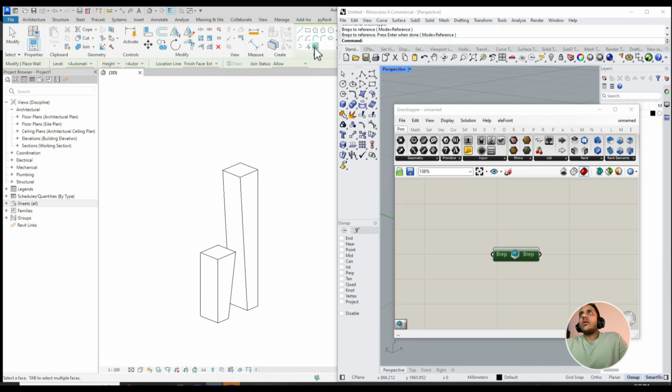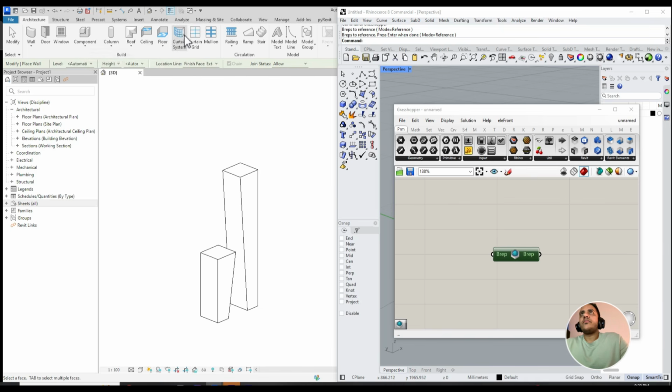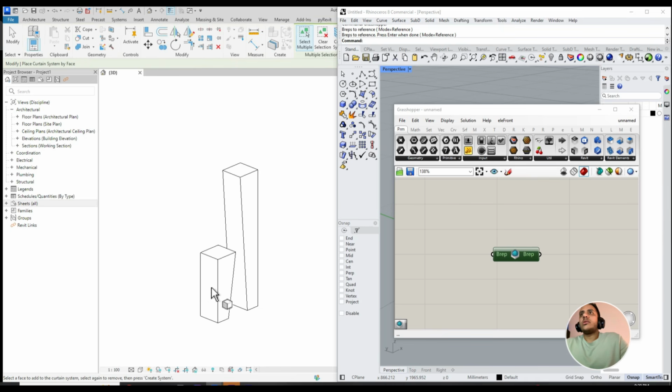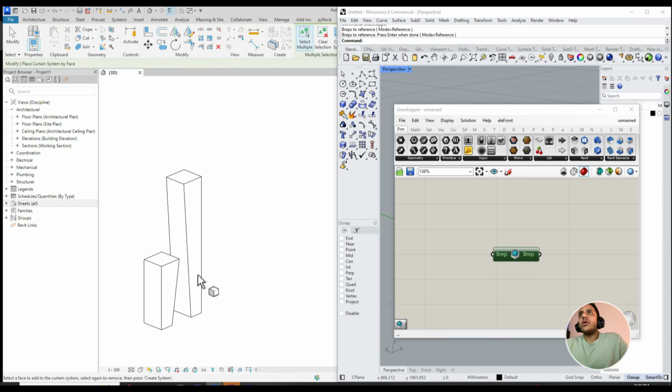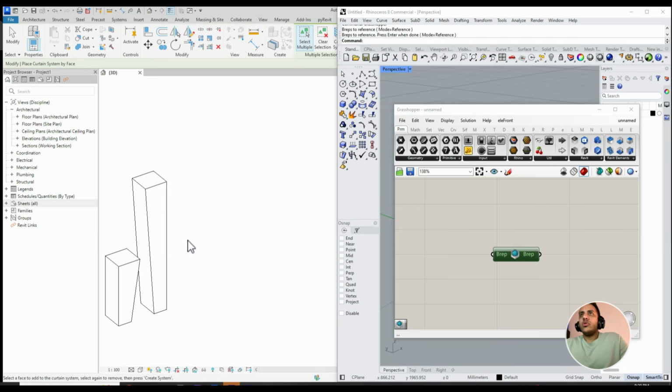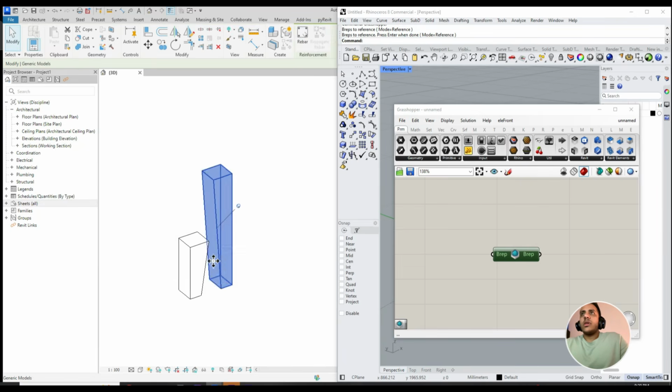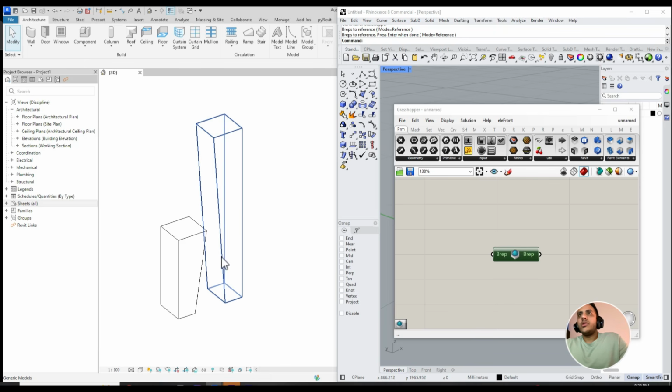If you want to pick a wall surface, or create a glazing system or something, it's not readable. You can use this way if you want to keep fixed geometry, decorative stuff, or something that you don't want to edit or work on in Revit.